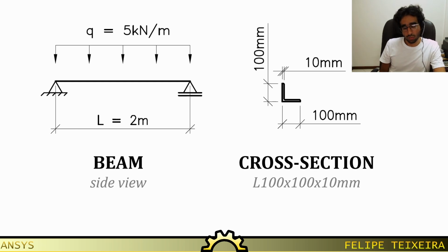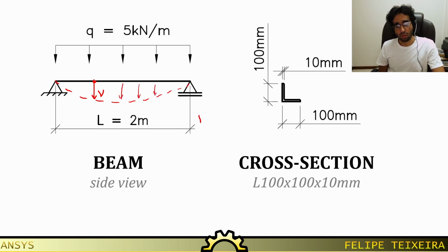Our objective here is also quite simply stated. We want to know the deflections of this beam. We know that given this load, the beam is going to deform like this. It's going to display a deflection, and at any point here I can calculate the value of the deflection, nu. This is not a v, this is a Greek letter called nu. So if I can determine the value of this deflection, nu, at every point along the axis of our beam, we're going to have the value of nu as a function of the coordinate x. X just positions our cross-section along the length of the beam.